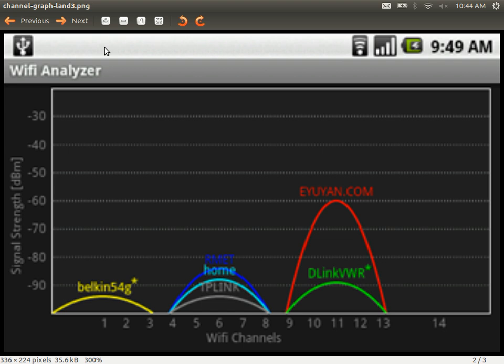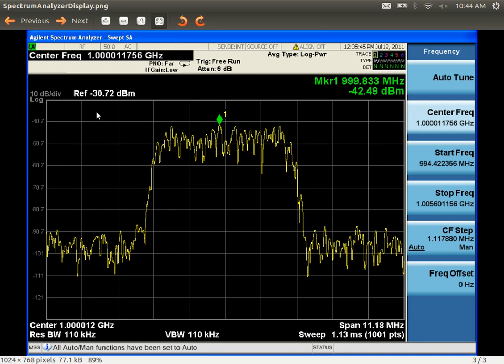And another example, again a plot of real signal strength, and we'll see it's versus frequency. These three plots that I've shown you, this one, the Wi-Fi analyzer and the spectrum analyzer, all show a signal in the frequency domain. That is, peak signal strength versus frequency. This is not time here, it's frequency. So we need to introduce this concept of frequency domain. Currently we've just spoken about the time domain, where you have the signal strength against time.